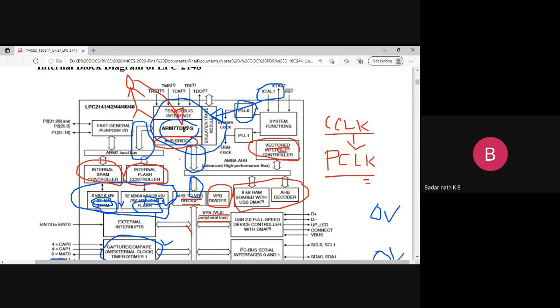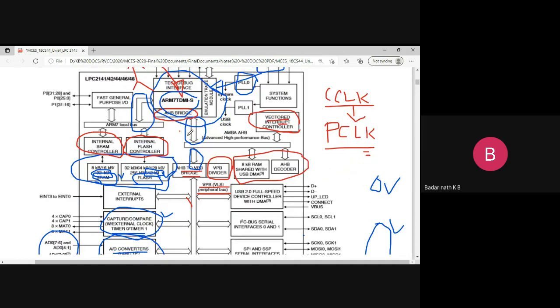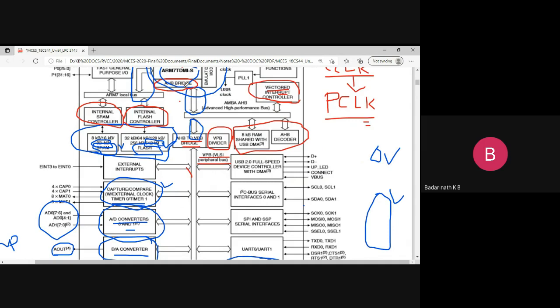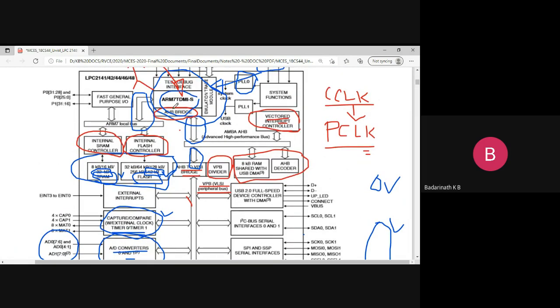But that consumes the power of your microcontroller. That means you lose the time of the microcontroller. Since the microcontroller has to do so many other jobs, you cannot use it for counting jobs. In such cases, whenever you want to generate delays or count certain events, we use what are called timers. Timers are hardware blocks used to generate different time delays and for counting applications, where you can relegate these jobs of the microcontroller to this block.